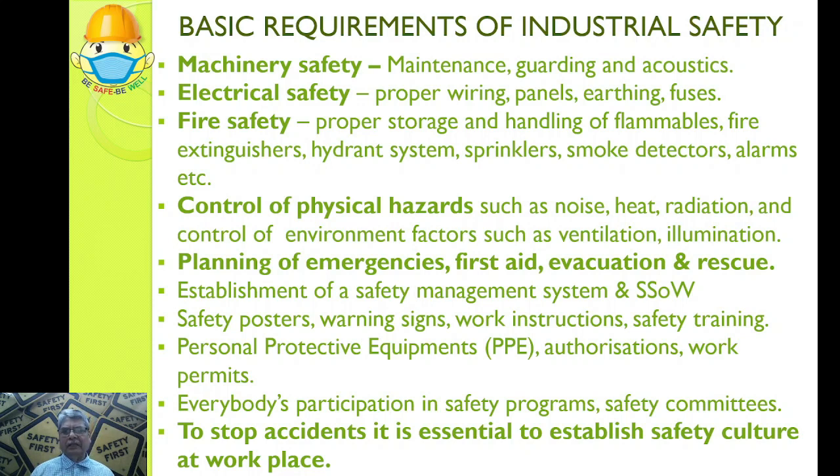For fire safety, there must be proper storage and handling of flammables. There has to be an adequate number of fire extinguishers of adequate size and type. There has to be an adequate hydrant system throughout the workplace. There have to be sprinklers at the required places like storages. There have to be smoke detectors, alarms, etc.